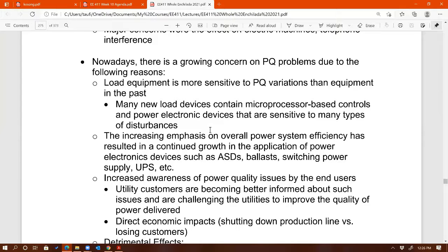Right? And that happens because the adjustable speed drive requires non-sinusoidal current from the transformer, and that non-sinusoidal current translates into distorted voltage, right? Because they're connected to the same secondary side of the transformer, that same distorted voltage is being seen by the PLC, and that's the reason why the PLC was not happy and it just shuts off, right?